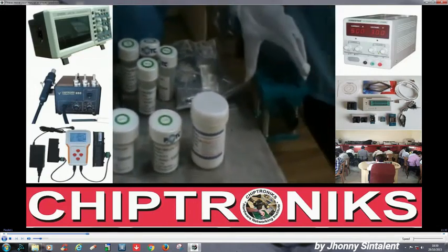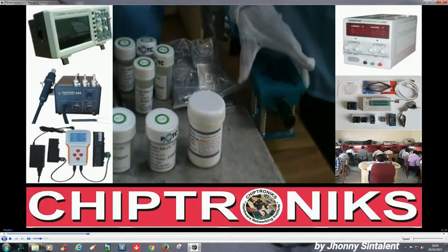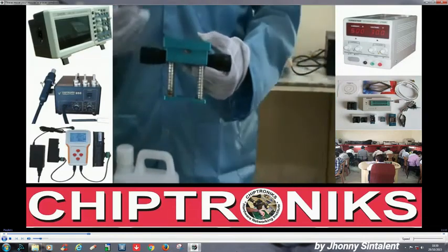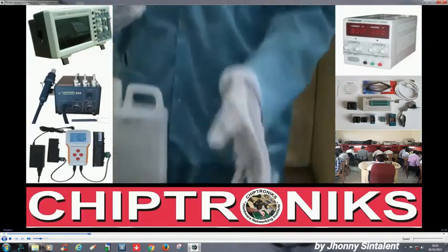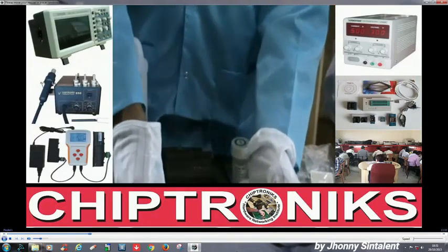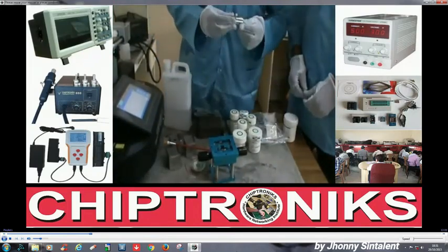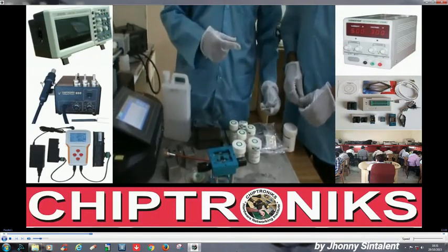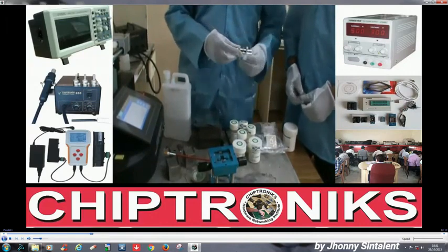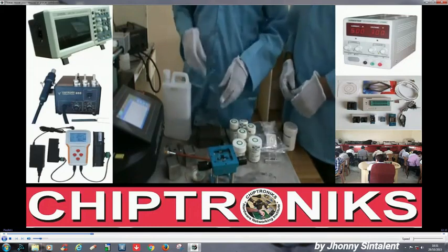And there is one more type, this is the indirect, non-direct heat stencil set. This stencil set and jig is used by beginners, one who is beginning with the BGA process. This is the stencil and this is the jig for the non-direct heat stencil. Whereas for direct heat, we have a very simple stand, and you can start using this initially also, but you require some practice while using the direct heat stencil. But once you gain practice, then this is better than non-direct heat.